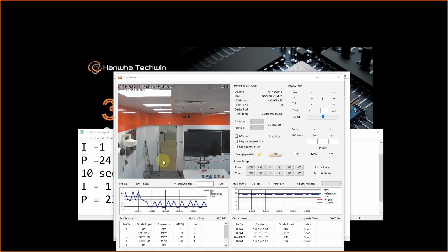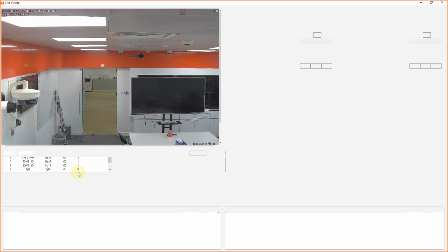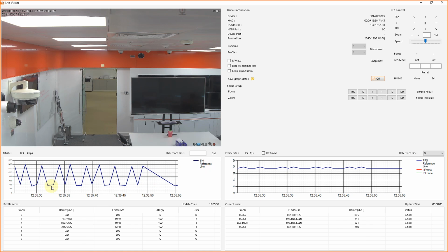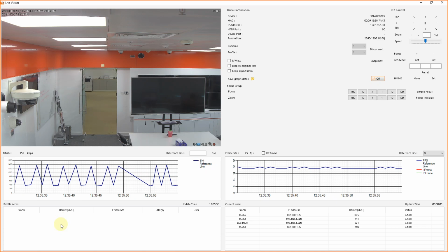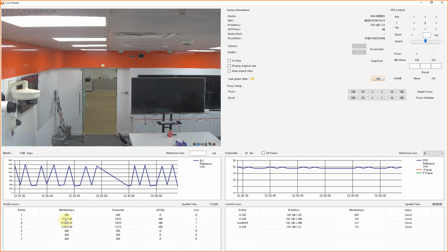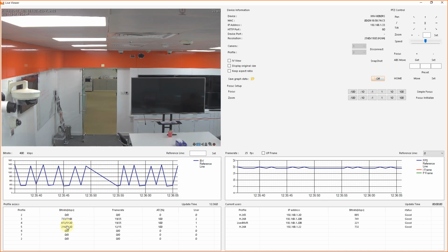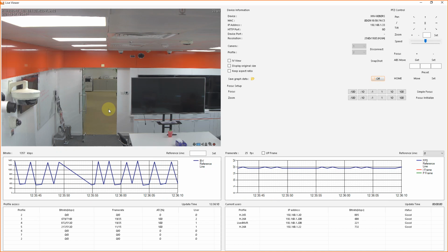However, if there is a moment, so right now it reduced, H.265 became 0.9, H.264 became 1.2. The new average is 0.7 and 0.8. Okay, I divide by 1000 because it was Mbps, right now kbps. So you can say it's less than 1 Mbps for a 5 megapixel camera, right? This is what the technology does.